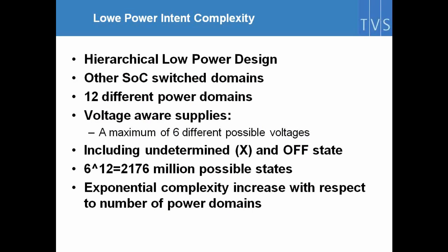In terms of complexity, the design has been cut and put in different hierarchical power domains. There are other SoC switch domains that are involved. We've also got inside the design 12 different power domains which have 6 different possible voltages.